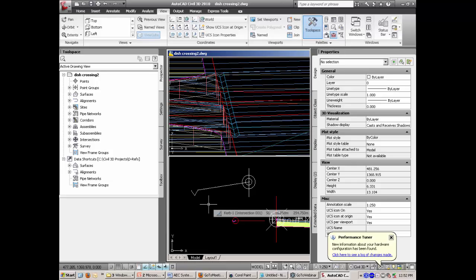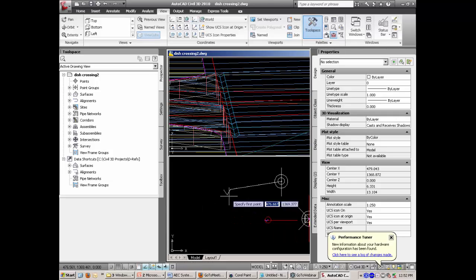So essentially, the software designs the road to the edge of bitumen and chucks in the V-drain afterwards. So you still get your same crossfall, and you build your dish crossing. You would obviously put in your curb and gutter here and work across from that side. So we can do more on the dish crossings. It isn't quite finished yet. In some ways, it's actually more difficult than the tunnels, believe it or not, because you have to take in the road crossfall when you're doing your V's. The tunnels, once you understand the concept, are quite a simple thing.